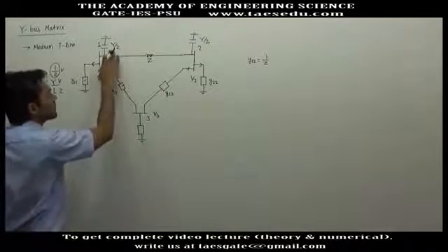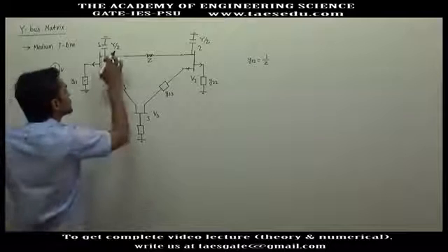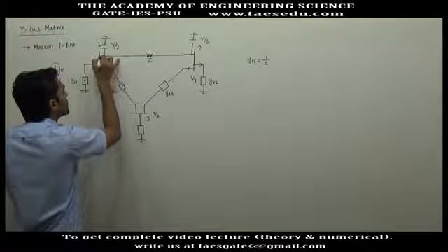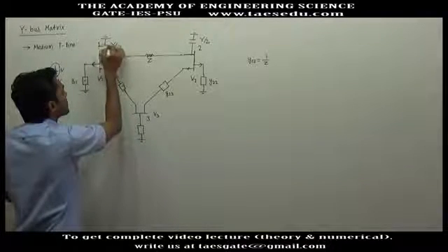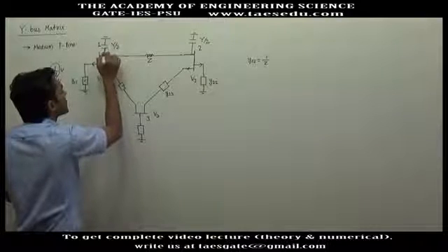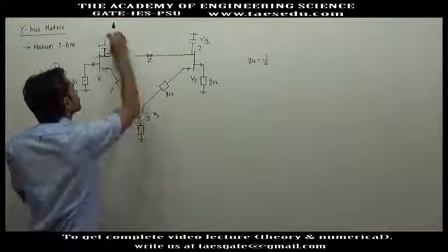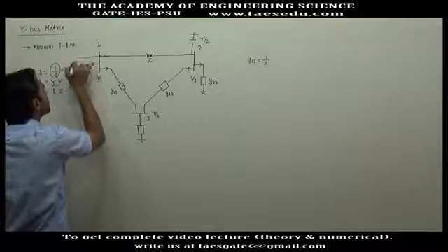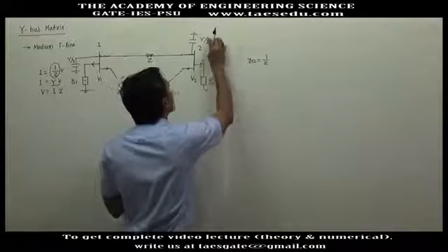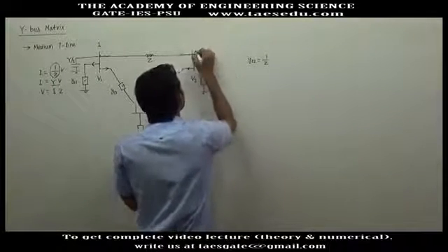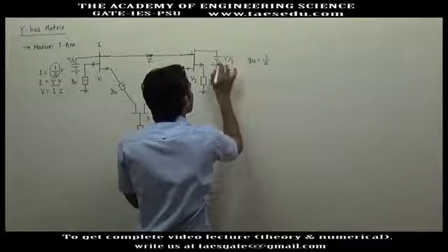Okay, now if the admittance part of the transmission line is connected at the extreme end of the transmission line, what is the extreme end of this transmission line? This is connected to the bus. So instead of connecting the admittance of the transmission line to the transmission line, let us connect it with the bus only, because these two points are the same. So this will be connected as capital Y by 2, and this will be connected to bus 2 only, capital Y by 2.